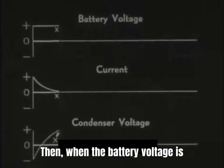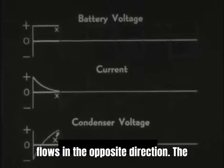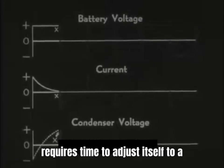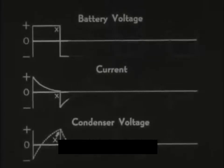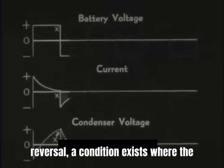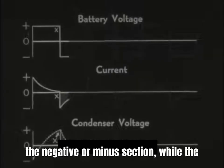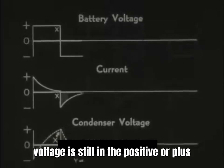Then, when the battery voltage is reversed, a heavy current immediately flows in the opposite direction. The voltage across the condenser, however, requires time to adjust itself to a negative value because of the resistance in the circuit. Thus, for a period of time following each reversal, a condition exists where the current has changed direction and is in the negative or minus section, while the voltage is still in the positive or plus section.